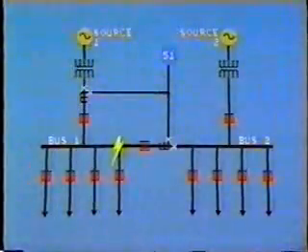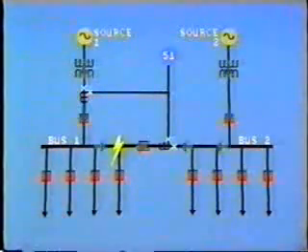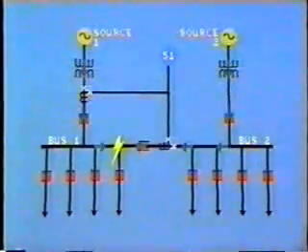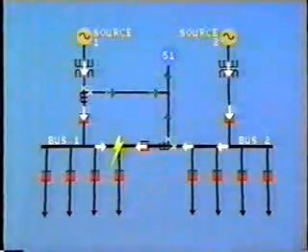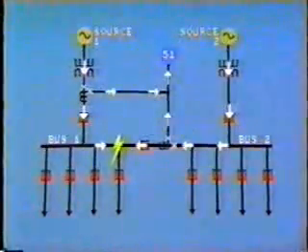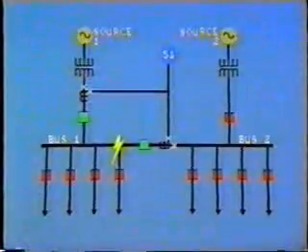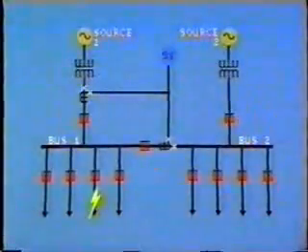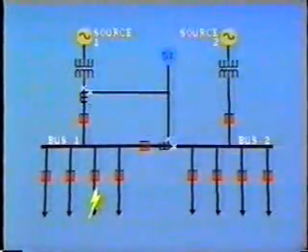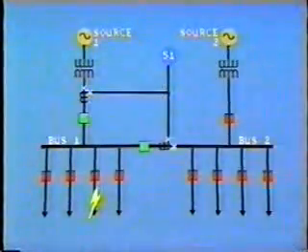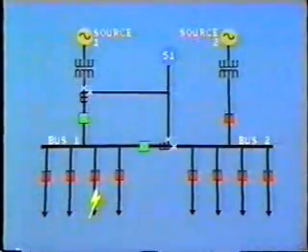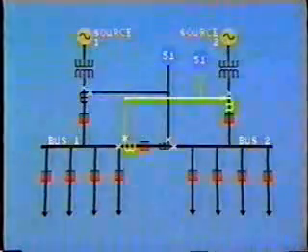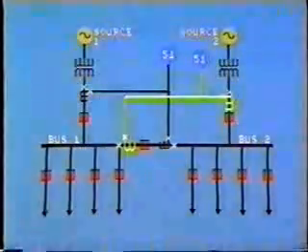Now, if a fault occurs on bus 1, then heavy fault current will flow into bus 1 from source 1 and also through the tiebreaker from source 2. The current in the two CTs will now be additive and consequently will cause the overcurrent relay to operate. This protection will also operate for a heavy fault on a bus 1 feeder, which fails to be cleared by its own breaker. The system therefore operates as backup, and the setting of the relay must allow for this. Of course, a similar pair of CTs will be connected to provide partial differential protection for bus 2.